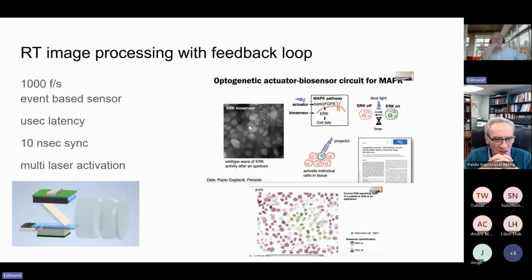When you do image processing or signal processing, and you have very fast processes, or you have a very tight control loop where you want to record 1,000 frames per second, or you need a lot of sensors very tightly synchronized, let's say like with a certain particle accelerator, there is no way that you could use a software-based solution like a Raspberry Pi.